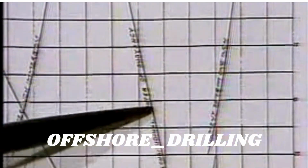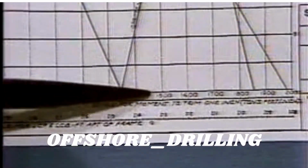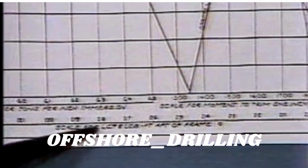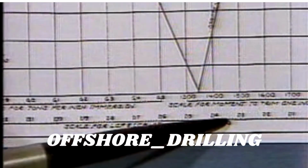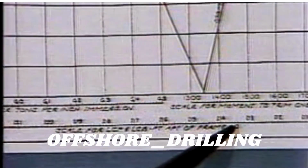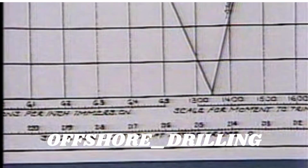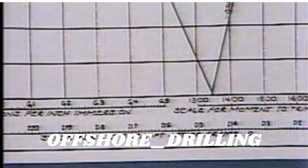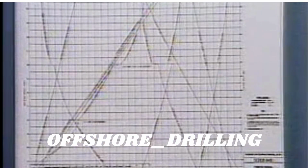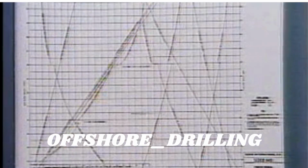Now we move vertically downward from this intersection point until we find the LCB scale. On this scale, we read that the LCB is 213 feet 6 inches aft of frame 0. You should remember that frame 0 and the forward perpendicular are the same point on the vessel. Now, this procedure is the same for obtaining any other information contained on this graph.